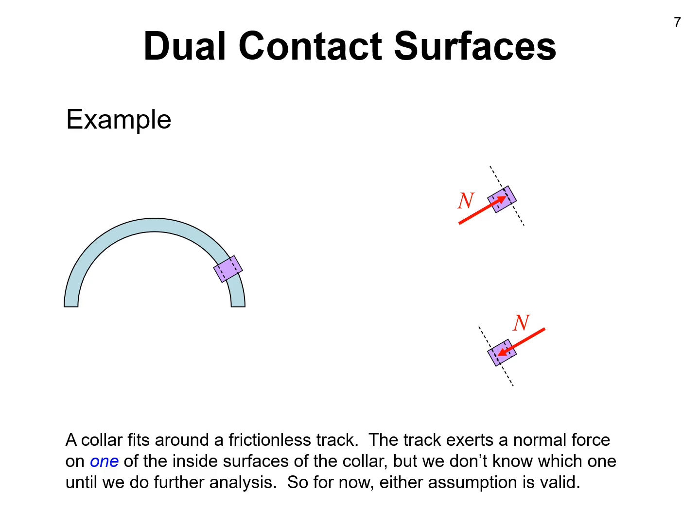So these are both correct assumptions, and again, later on when we solve equations, we would determine how the answer of the equation dictates which one it was. But for now, at this point in the course, you would be okay to draw on either side. But we don't usually draw both at the same time because there's never such a thing as a perfectly tight contact. There's always some tolerance, and for different reasons that we'll see later, we'll assume that only one of the surfaces is in contact and the other one is not.